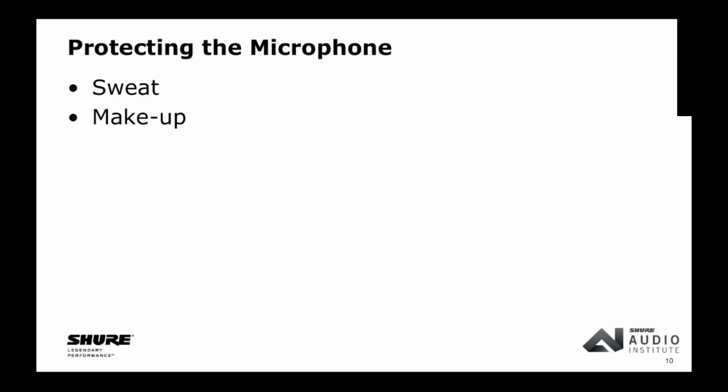And you'll see that actually on some head booms. You'll see a little tiny sweat prevention plastic shield donut piece that they put right behind the element. We've got it on a couple of ours, but the O-ring's a great idea for something that doesn't have it. Exactly. Those are really the main techniques and we just play with the exact mic placement, and then the final thing is just keeping that person as dry as possible. So when they come off stage, you have somebody there with a towel, and they blot their head and try and get as much of the sweat off of their head as possible. It's unrealistic to not expect sweat out of microphones. Completely unrealistic.